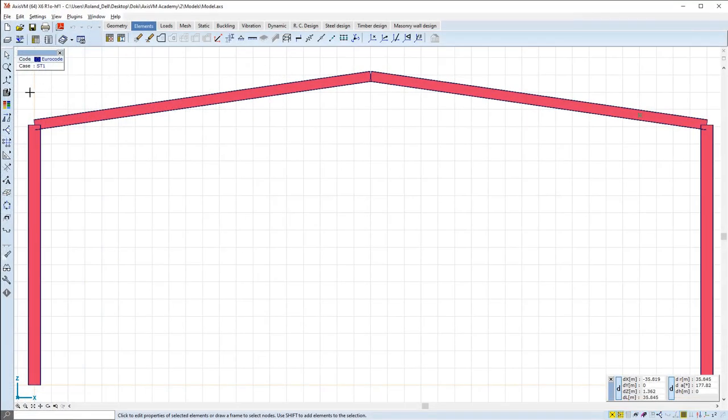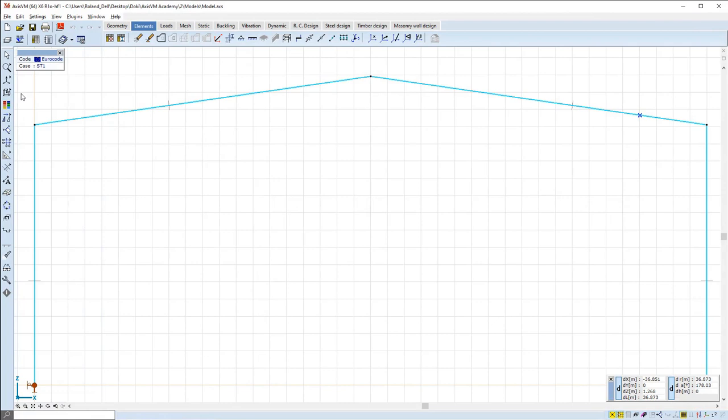After we have applied cross sections to our geometry, the next step would be to add the hinged segments to the two sides of the beam. For this we will need to break the beam element into two segments, and first step to do this is to introduce an internal node onto the beam.